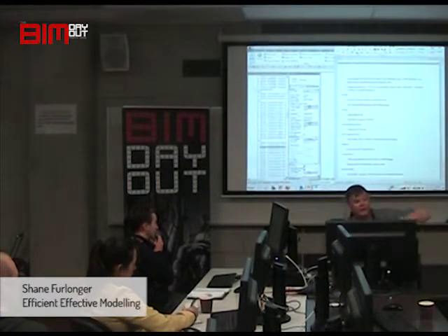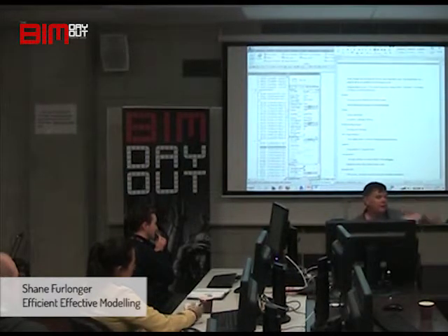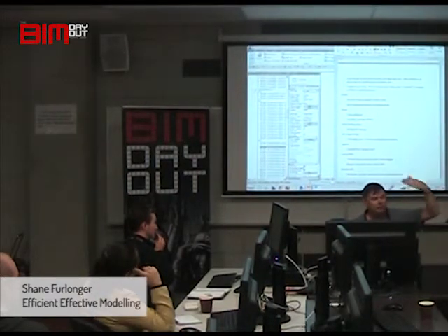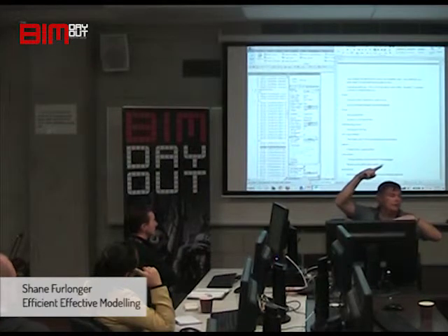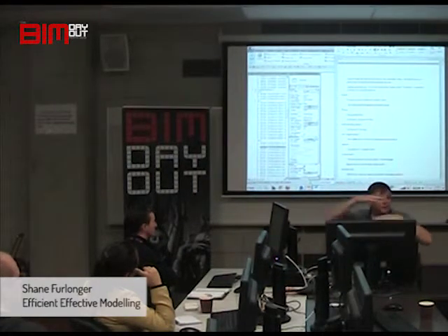If your floor heights change between the levels, you've got to create a different group because otherwise the walls won't go to the height above. Yeah? Because it's in a group, it's locked.